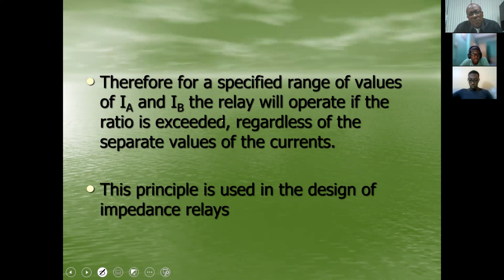Because in terms of voltage disturbance, you're more likely to have a voltage collapse as against a transient situation where you're overshooting system voltage. And what you see, for example, the distance relay is that it operates if the impedance falls below a certain value.